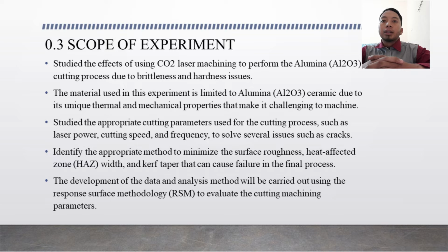Study the appropriate cutting parameter used for the cutting process such as laser power, cutting speed, and frequency to solve several issues such as crack. Identify the appropriate method to minimize the surface roughness, heat affected zone width, and kerf taper angle that can cause failure in the final process. And last for the scope, the development of the data and analysis method will be carried out using the response surface methodology or RSM to evaluate the cutting machining parameter.